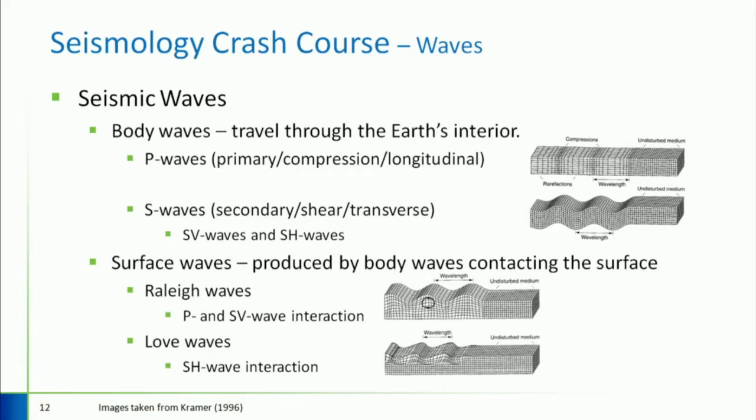A shear wave is one where the contacts are moving perpendicular to the direction of flow. So if you've got two particles connected and you slide one on the other, it'll pull the other one with it, and you get this slinky-type wave that they call a shear wave because of the mechanism that contributes to the propagation of this wave. When they hit the surface, they do different things. Because there's nowhere for the wave to transmit, some of it gets rebounded, and you get these random features, whether they be circular or different motions within the ground surface.